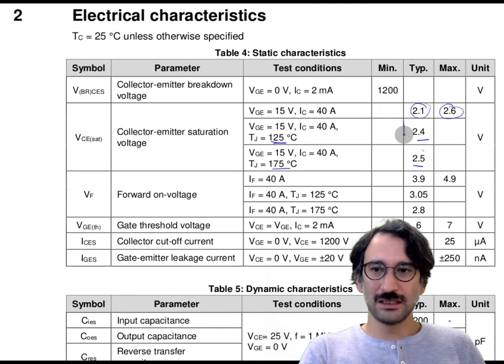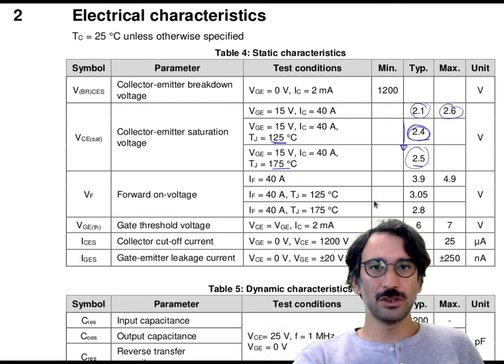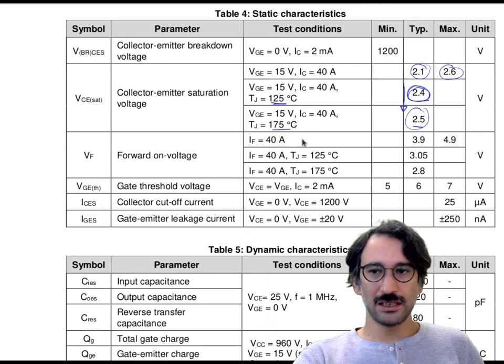That's quite dangerous, because if you didn't design your thermal system properly, this will cause some power loss, then it will heat up to 125 Celsius, then it will create even more power loss, then it will try to increase the temperature, so there can be a thermal runaway. So there's a feed forward mechanism here.